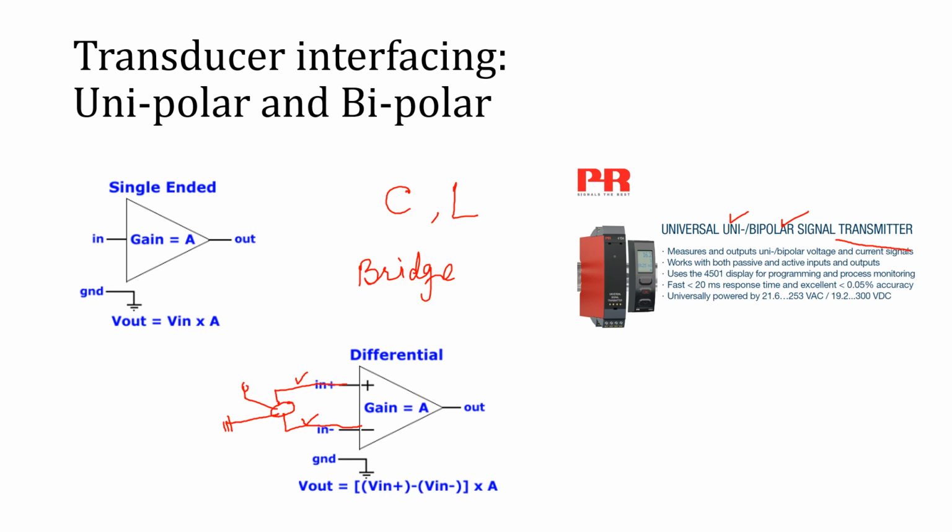So it depends upon the transducer. If we have a resistive transducer, we will use the Wheatstone bridge. If we have capacitive, then we can use the De Sauty and other capacitive bridges. And if we have inductance as the variable for the physical phenomenon, then we can use inductive-based bridges like the Wien bridge or the Hay bridge.